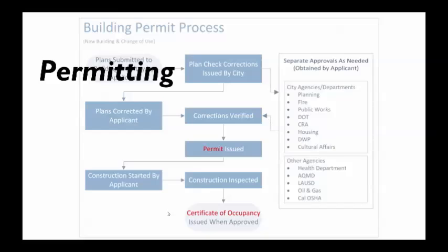And when a building project gets a permit, it will list out all of the inspections that are going to be required. So that might be a concrete inspection, framing inspection, mechanical, electrical, plumbing. And so it's the contractor's job, as each one of these phases of the project is built, that they call the city for an inspection. The inspector comes out, says, yes, that's okay, no, it's not okay, and then they need to pass each one.